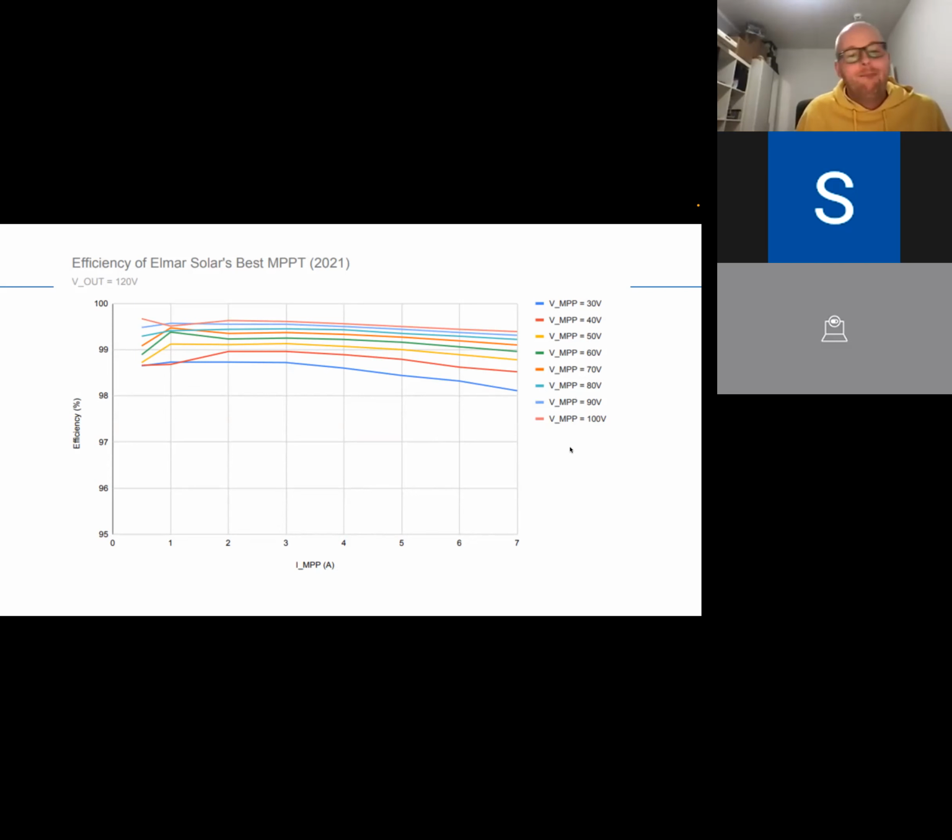So with regards to MPPT conversion efficiency, you want to make your solar array groups as big as possible. But that's again worse for your tracking efficiency, because then you're combining multiple cells that might have different irradiances. So there's a little bit of a trade-off here.